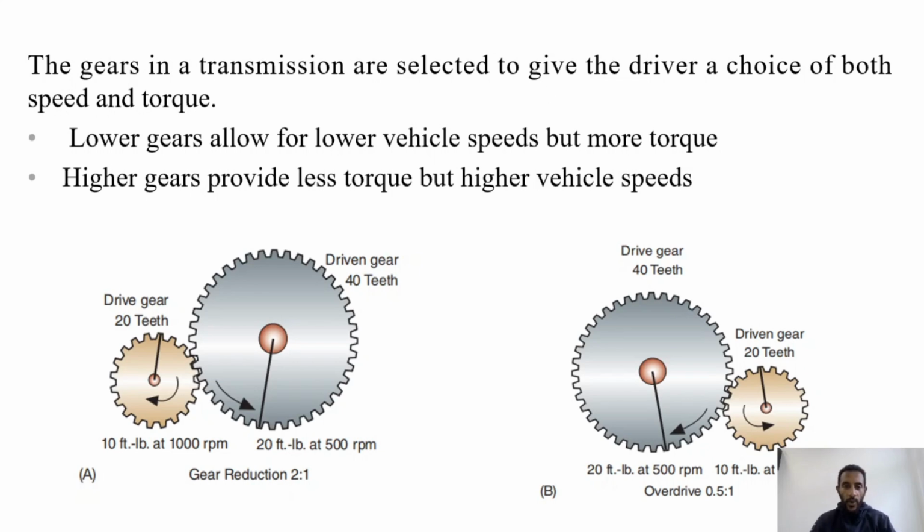understanding in Amharic, because in Amharic, if you say higher gear, it means this will have too much torque, or they call it heavier gear. So in this part, the key concept is that the torque input and the torque output will vary, or the speed input and the speed output will vary by changing the number of teeth on the gear, or the diameter of these gears, or the diameter of the pulleys, or the sprocket. You can understand or differentiate from different perspectives.